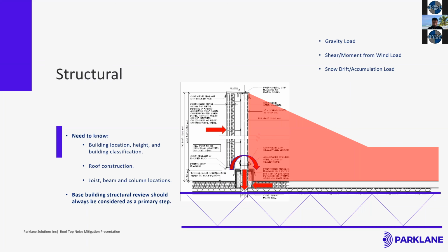And it's not just that, you also need to make sure that the dead load and snow load, all of that is being accounted for. And if it is for an old building, you want to make sure that the building can actually withstand that additional load going onto the building. So that's a very key aspect. Typically you wouldn't have structural drawings for an old building, in which case you would have to do a structural study just to make sure that the existing structure can actually withstand the additional load that's been imparted onto it.